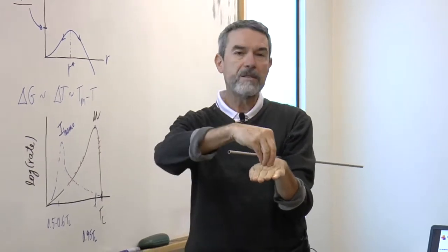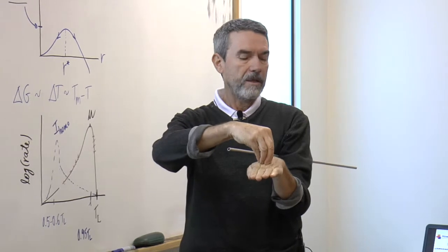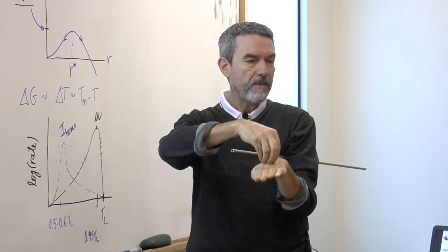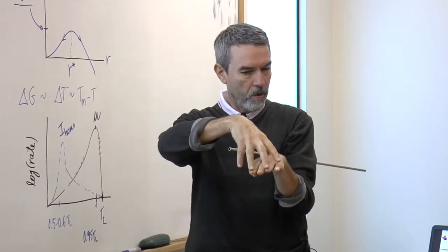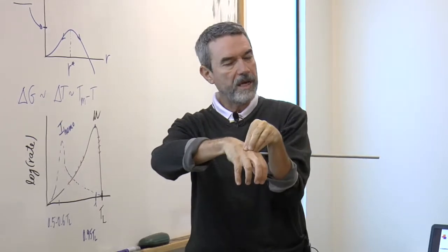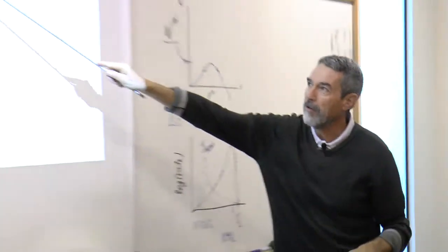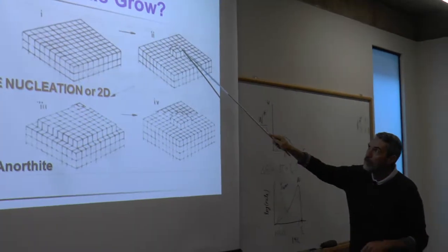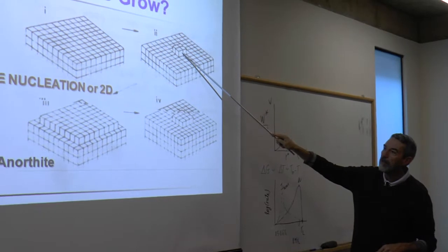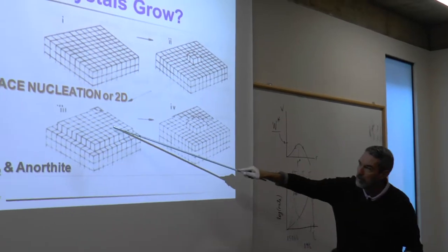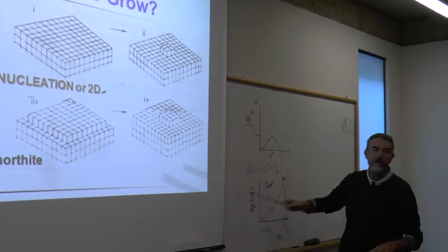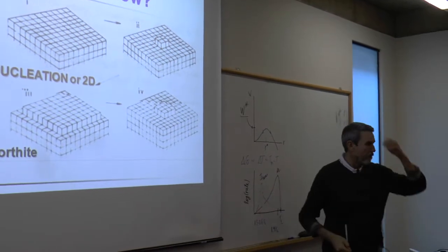So there's a secondary nucleation, and then this secondary crystal grows, then there is another nucleation event and it grows and so on. So there's a secondary nucleus formed here. It grows, and then there is another one formed here, and that's how the crystal grows.